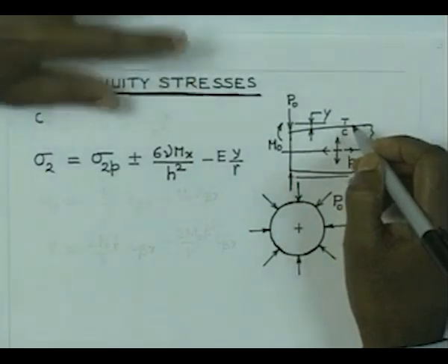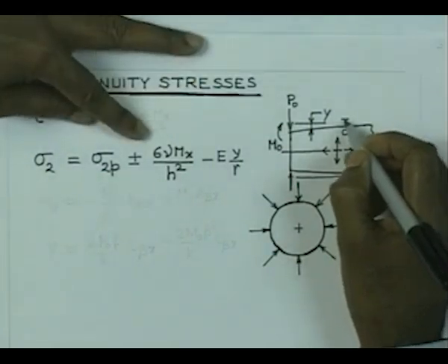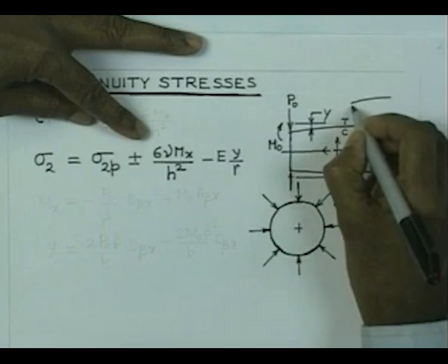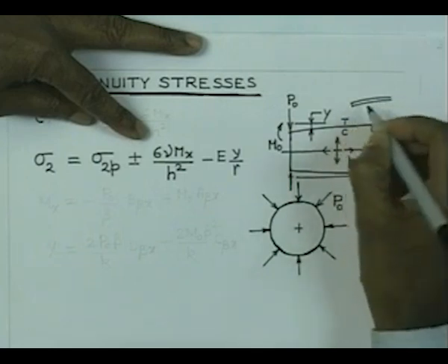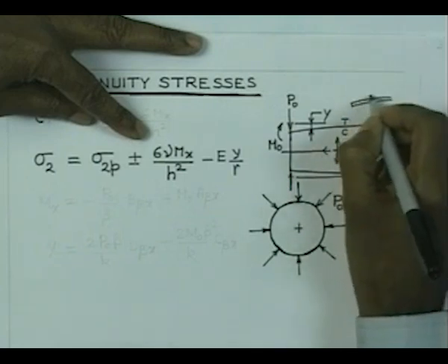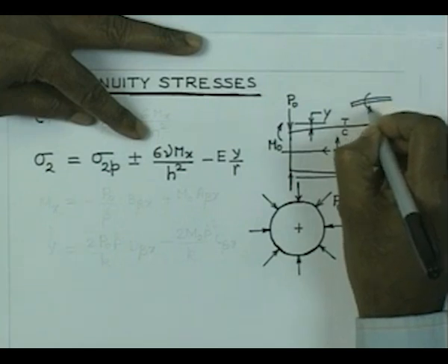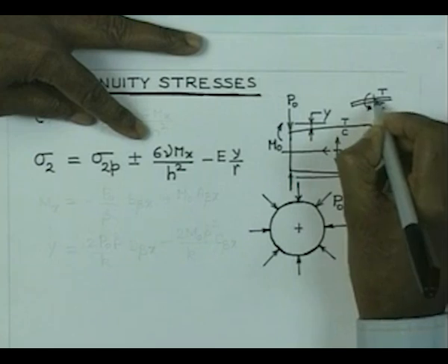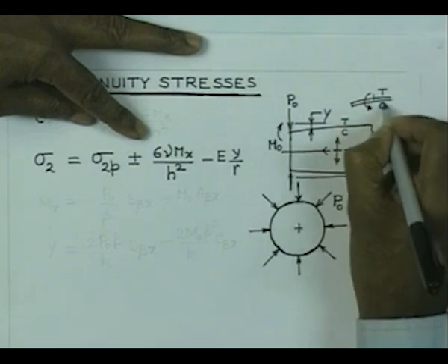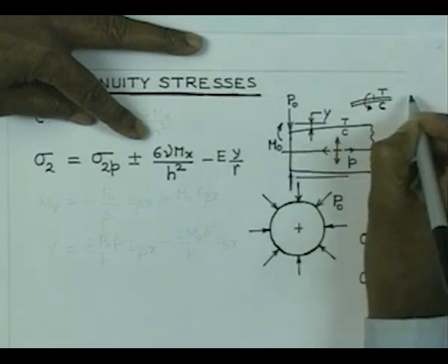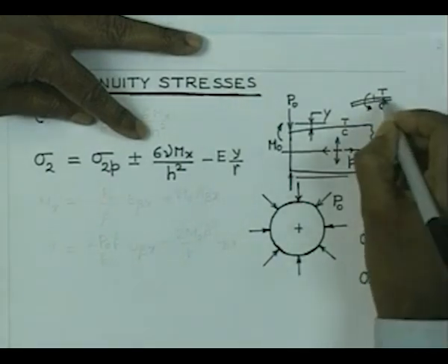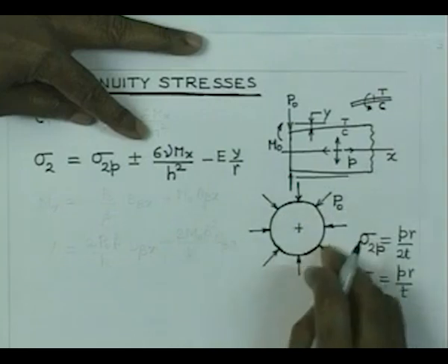Now, I think I will just repeat again that you see that because of this bending, let me draw that wall, I am sorry about this. So, if we draw this, because of the bending moment acting at this section, you are going to get tensile stress there, compressive stress there. So, when it is having tensile stress in the longitudinal direction, in the circumferential direction it will try to contract, and that contraction will be prevented because of this continuity of the cell.